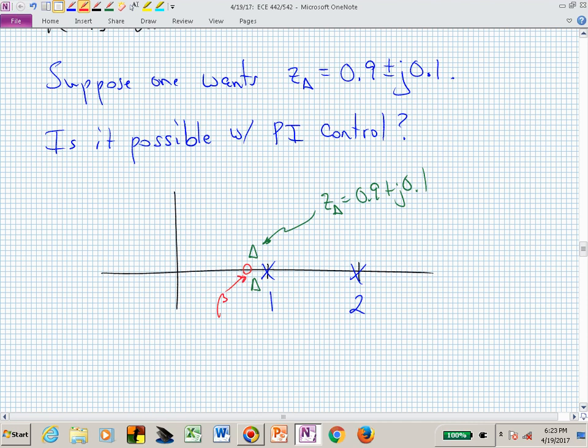If those triangles are not on our root locus, what do we know has to happen at those triangle locations? Do you remember? What determines the shape or the location of our closed loop poles? They have to be satisfying that 1 plus kg bar of z equal to 0, which means that kg bar of z has to have an angle of what?